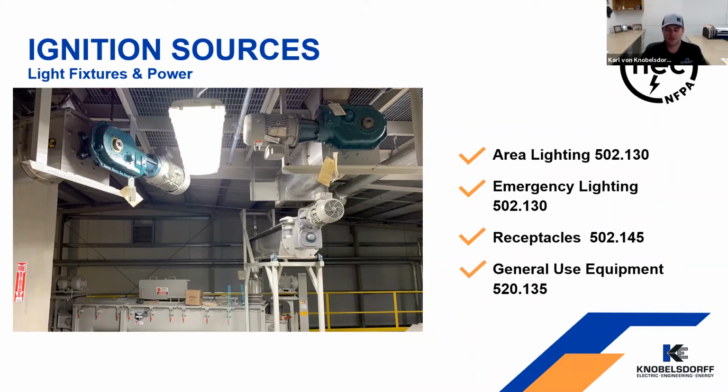So there's many feed mills, flour mills, grain elevators that have Class 2 Div 2 ratings that have normal receptacles with weatherproof covers. That does not meet code at all. Why that was allowed to get installed that way, I never could figure that out, but there's lots of facilities that are like that.